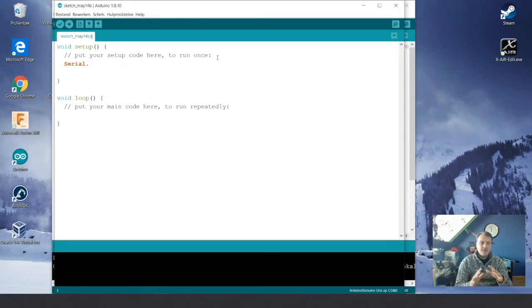Don't worry about this. You just need to have a specific baud rate, and you need to have the same one when you're reading out the Arduino and when you're sending information to the Arduino. When you're communicating between two PCs, they need to work in sync. They need to have the same speed of reading, and that's what we call a baud rate.